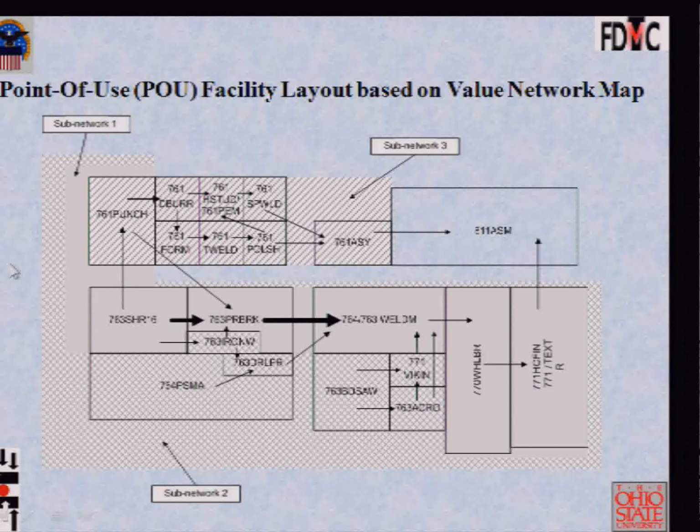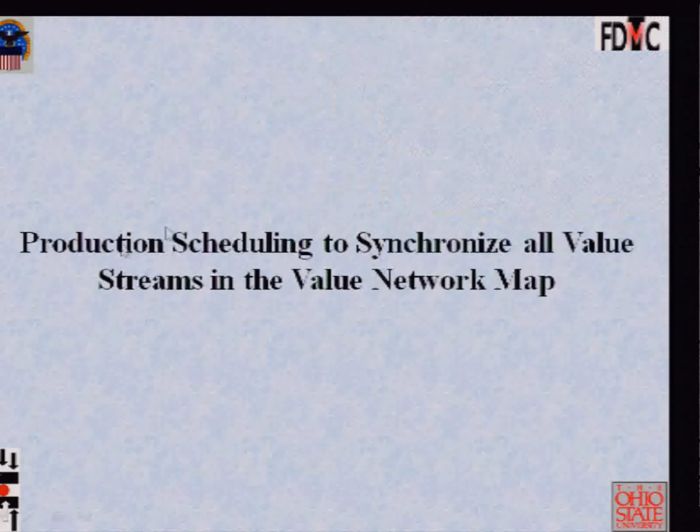in a complicated facility. You still have to schedule production. Why? Because there are many components going through many shared resources. And I don't think you can do it by hand. So even if software tools like Preactor or Optisol or Tactic may schedule heuristically, at least they do feasible capacity constrained scheduling. Let's do that rather than use wrong methods like value stream mapping and takt time and Kanban squares and Hijinker. So this is step 4 in the lean thinking process.